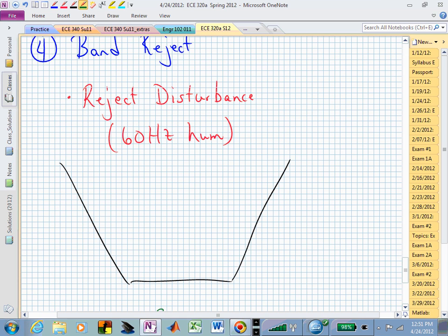What do you know is happening at low frequencies? Here's the low frequency, and what gives you that, and let's say that it's always coming down, it's never flat for low frequencies. That now corresponds to a pole at the origin. So now we have a pole at the origin.